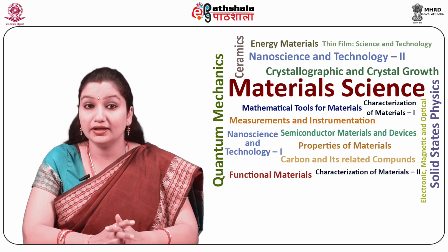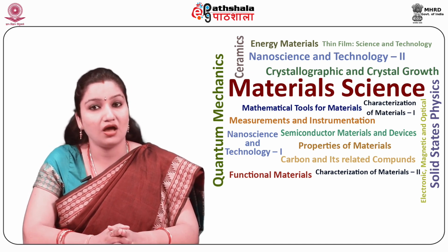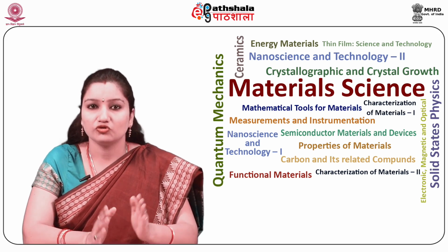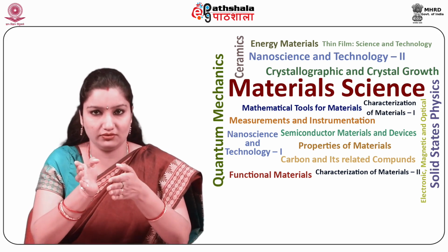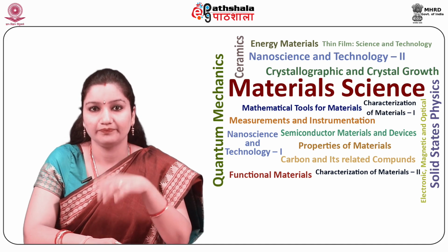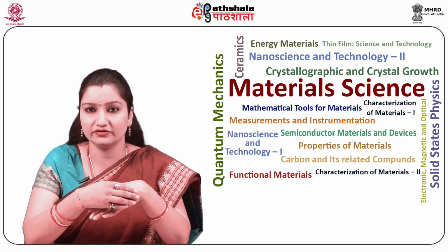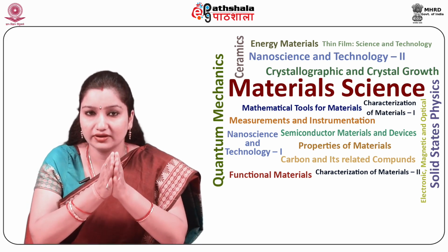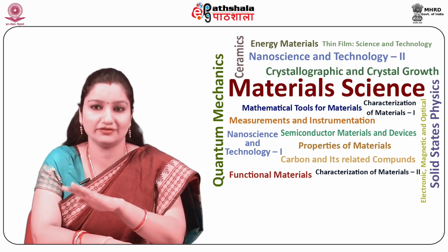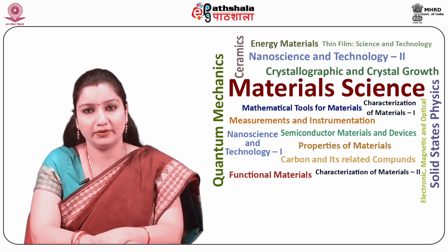Hardness. Another mechanical property that may be important to consider is hardness. Hardness is a measure of a material's resistance to localized plastic deformation, for example, a small dent or a scratch. Quantitative hardness techniques have been developed over the years in which a small indenter is forced into the surface of a material to be tested under controlled conditions of load and rate of application.